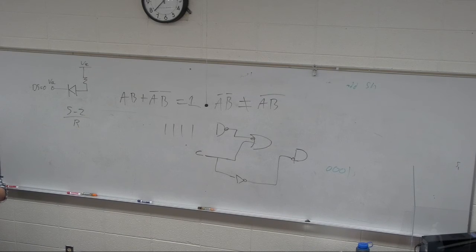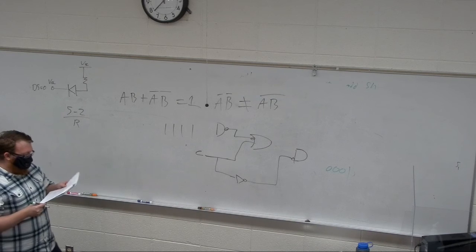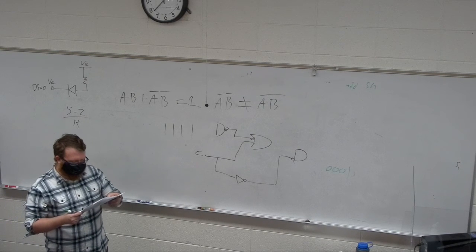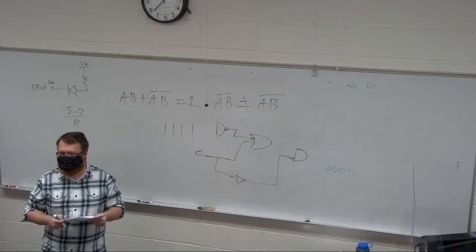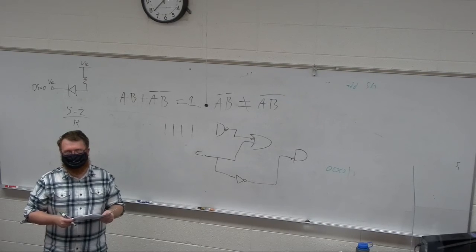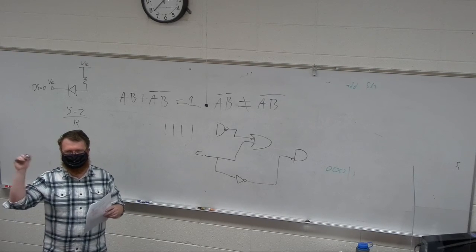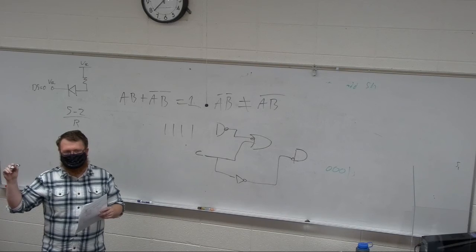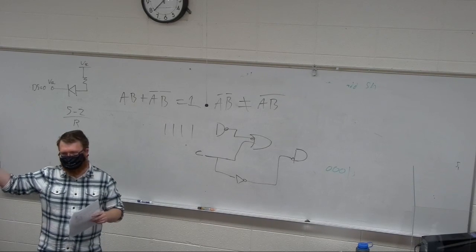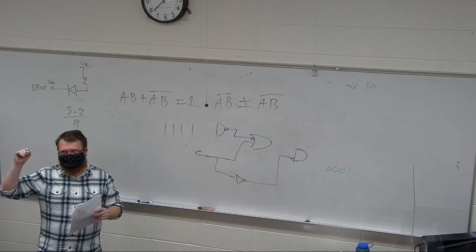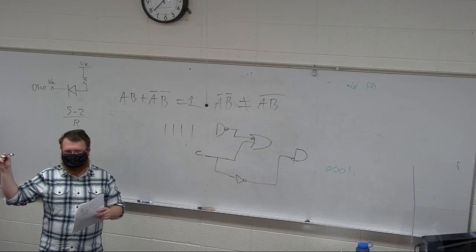13 was excellent. Good job. You guys learned from the homework. That was just 15 millivolts times 18. The only mistake that really happened is you multiplied by 18%, so 0.18. But it's 15 millivolts per percent, not per 100%, if that makes sense.